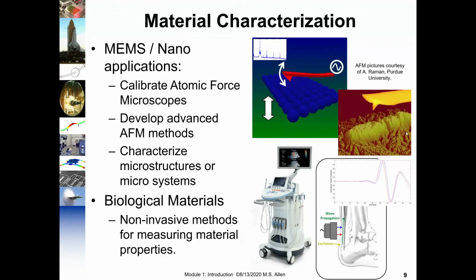There are other kinds of tests that are done that I'll hit on quickly, and the things you learn in this class will help, though we won't directly do a lot of this. But testing is also used to characterize materials. So if we have a material that's new and we want to know what its stiffness is, its mass distribution, properties like that, we might do a vibration test.